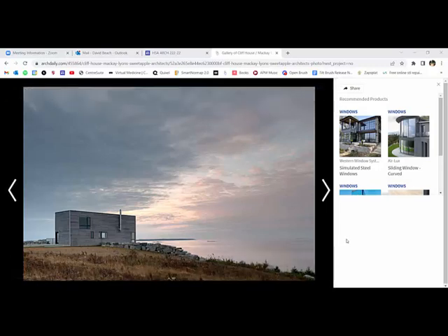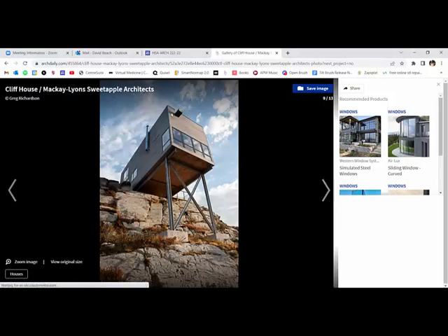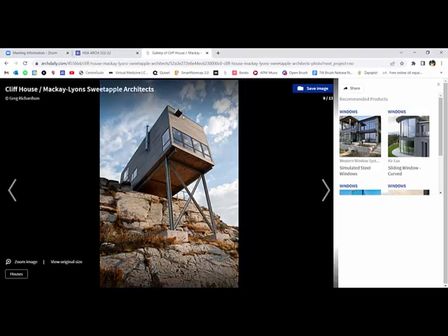So what we're looking at today in particular is modeling a few of these very important, relevant exterior pieces. And if we have time, we'll also go through this X bracing. All of those, for right now, with where you're at on Revit, are going to be best modeled by using generic components. Okay, so that's going to be the technique that we're going to use. So let's start with the easy one, which is this little piece right here.